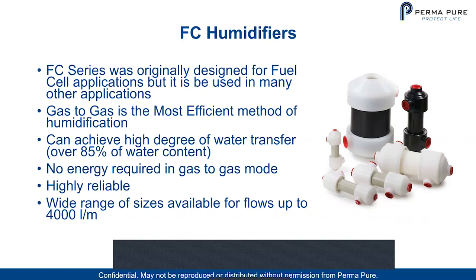So with our FC series humidifiers, these were primarily designed for fuel cell applications, but they're used in many other applications. And they're designed for gas-to-gas humidification. We can achieve a high degree of water transfer, up to 85% of the water content in the gas-to-gas mode. In the gas-to-gas mode, no energy is required. It is highly reliable, and there's a wide range of sizes available for flows up to 4,000 liters per minute.